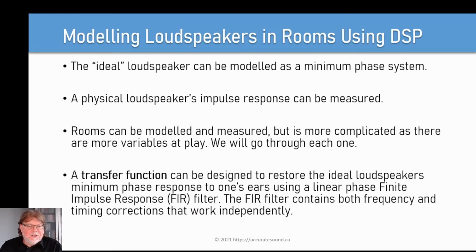A physical loudspeaker's impulse response can also be measured, and we'll be getting into that shortly. And rooms can be modeled and measured, but it's more complicated as there are more variables at play. We'll go through each one. In the end, a transfer function can be designed to restore the ideal loudspeaker's minimum phase response to one's ears using a linear phase finite impulse response, or FIR filter. The FIR filter contains both frequency and timing corrections that work independently.